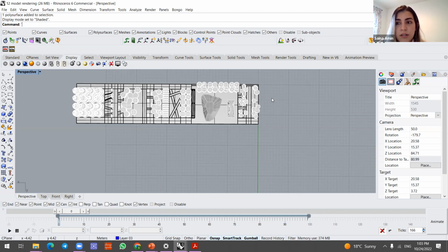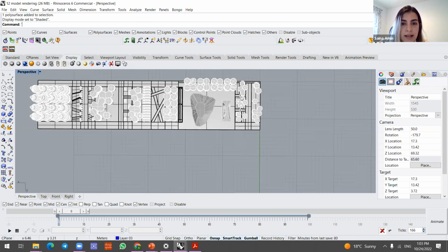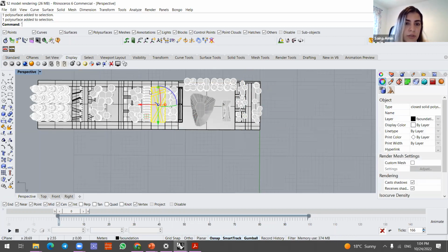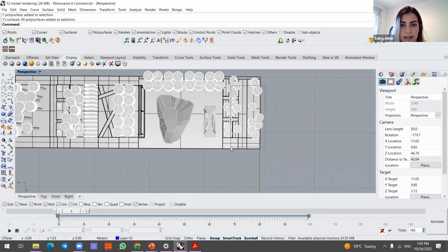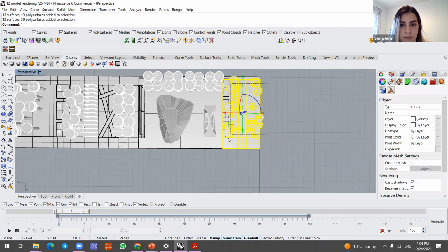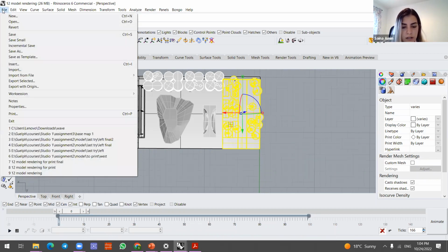You should check the direction and dimension of the surface of the 3D printer, and divide your site into those pieces. For example, I divided my site, as you can see, into 1, 2, 3, 4, 5, 6, and 7 areas. And for every piece, you don't need to export and make a new one. When you want to export the STL file, you just select the part that you want. For example, I want this one, and go here. As you can see, there is